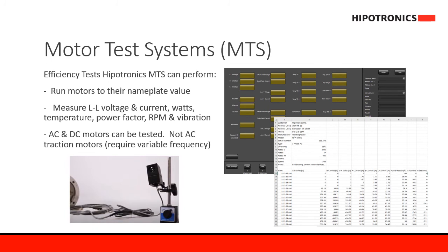On this slide, we can see the efficiency test Hipotronics MTS system can perform. They can run motors to their nameplate value. The MTS can measure line-to-line voltage and current, watts, temperature, power factor, RPM, and vibration.